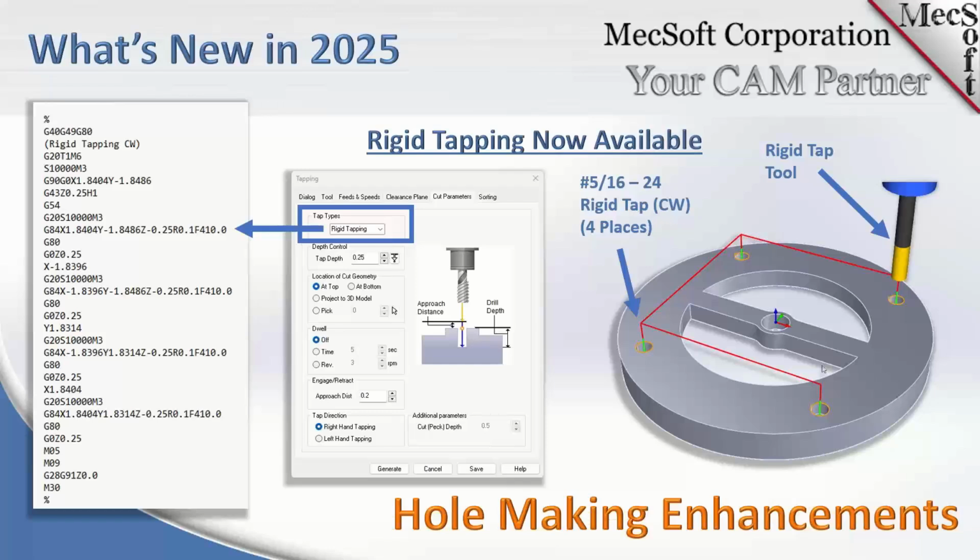I should back up and reword that. If you're using the rigid tap, then if you look at the canned cycle over here, it outputs the requirements for the controller to calculate the feed rate, the cut, and the RPM, the spindle RPM being most important. In regular tapping, the tool is actually a floating tool, where the tapping is done inside that floating area.